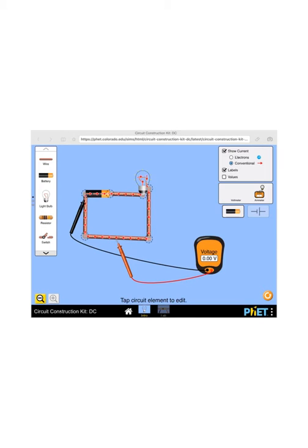In order to read a voltage, we need to be reading across some sort of device. And what's more is a voltage is only read between the location where two leads are placed. So I don't read any voltage difference across this wire length along the bottom. But I do read a voltage difference across the leads or terminals of a battery.